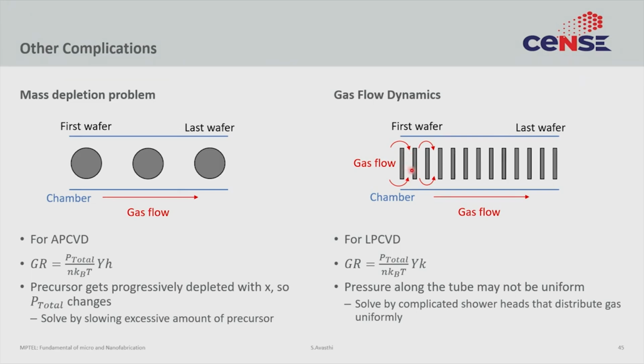The wafers are placed very close to each other, there is essentially a stagnant layer here. So, even in an LPCVD reactor there is a little bit component of diffusion in axial direction, because in reality this is a 2-dimensional problem and not a 1-dimensional problem, and all these issues complicate the design of the LPCVD reactor.